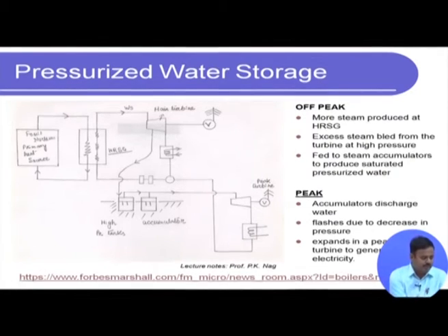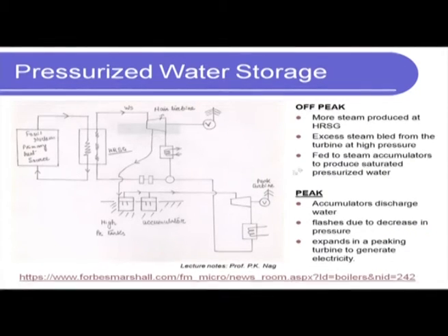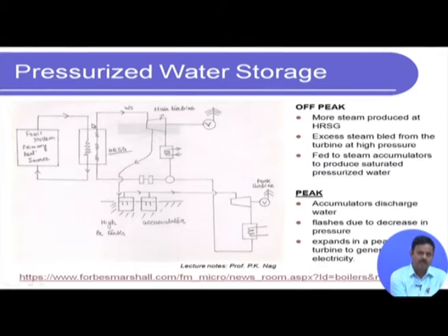Now, pressurized water storage, what do I mean by that? The way it is done is, when we have excess energy production, basically when the energy produced, let us say by a steam turbine over here, is more than what I need, during off peak hours, part of the high pressure steam that enters the turbine is extracted out at the high pressure stage itself, before it is expanded.